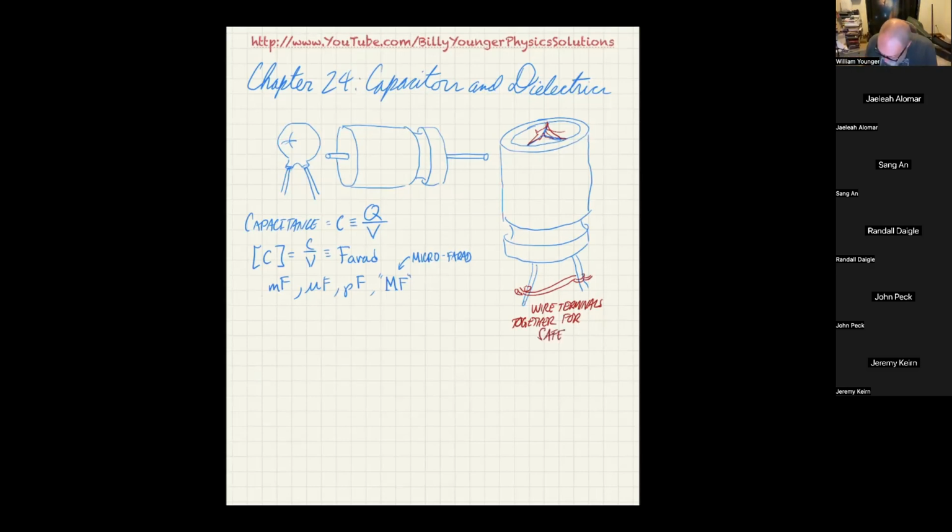Wouldn't that short it out? Yeah, it does. And there's some danger, of course, when you're doing that. You don't want to just grab a piece of bare wire and do it, because that would be basically summoning the shock to come get you. But what you normally do is you use a grounded line, and you touch the grounded line to both sides, one at a time, and then you can wire them together.